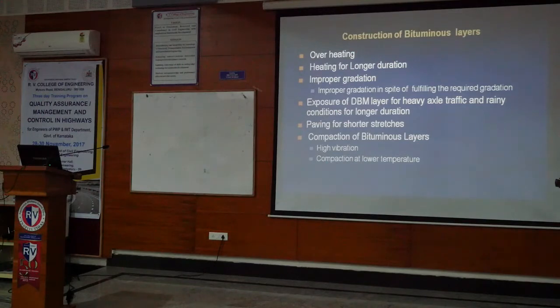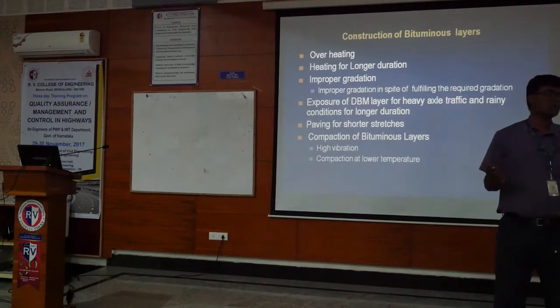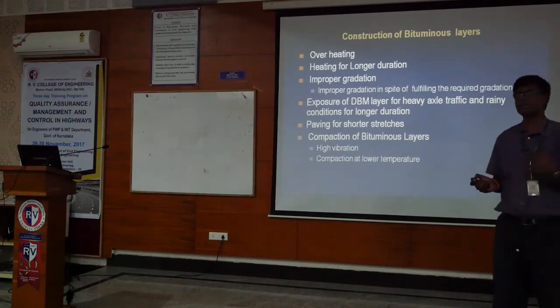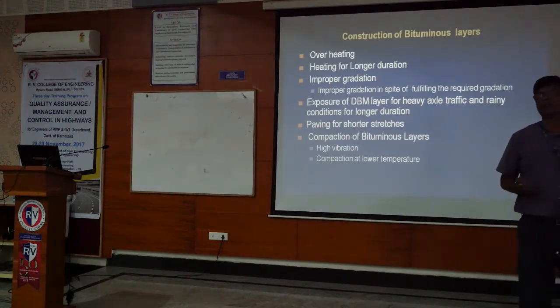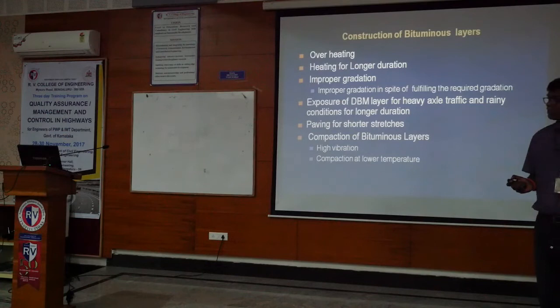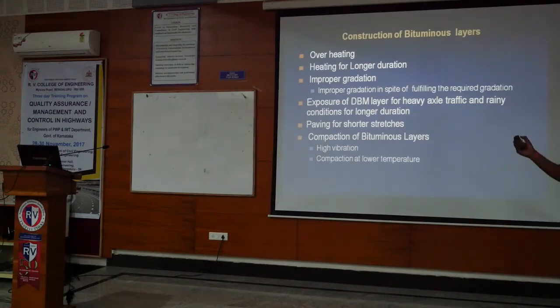Overheating, because my stretch is too far, and I don't want the mix temperature to come down below the requirement so that I get blamed. So what I do is I heat my mix more than the requirement, and that is dangerous. If I overheat the mix more than specified, I lose my sticking property. Hence the life of the bitumen comes down.